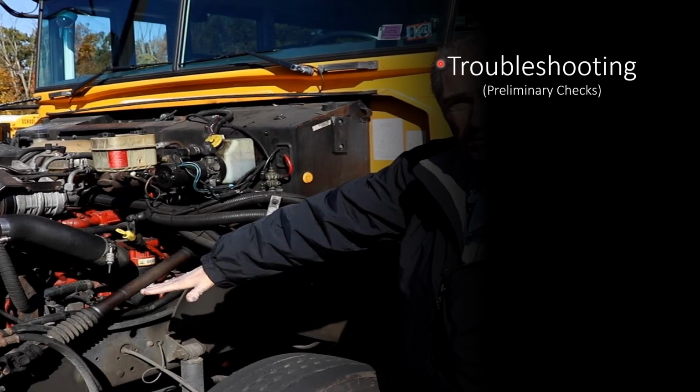Now, a lot of technicians like to skip that first step and just get into the preliminary checks. They want to get straight into visually inspecting the unit and seeing if they can see the fault or the issue before they even diagnose anything. And that's what you should do. You should just open up the engine compartment and start doing a visual inspection. Sometimes you can see if there's oil in the condenser or if there's refrigerant leaking out of one of the hoses. You can see it just by doing a visual inspection, and that's what we're going to do first. We're going to do preliminary checks.